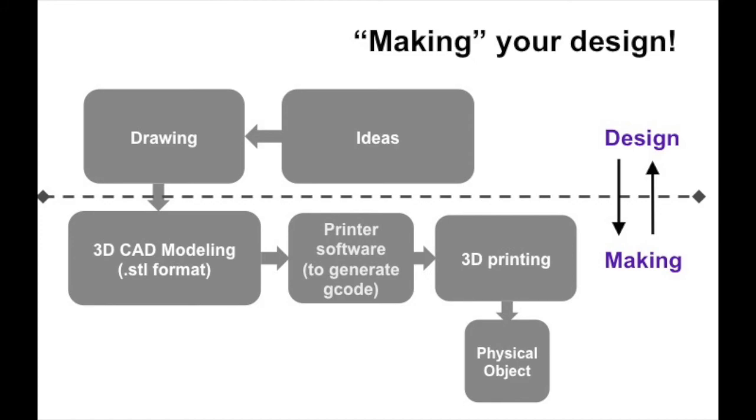At this stage, you will be able to adjust the size of your design, and you will also know how long it's going to take to print your design. The process of printing may take 20 minutes to days, depending on the size and the quality of your design. In the end, you will get your design in hand. Remember, this process goes like a design cycle, which involves multiple design and making iterations till you get the ideal products.